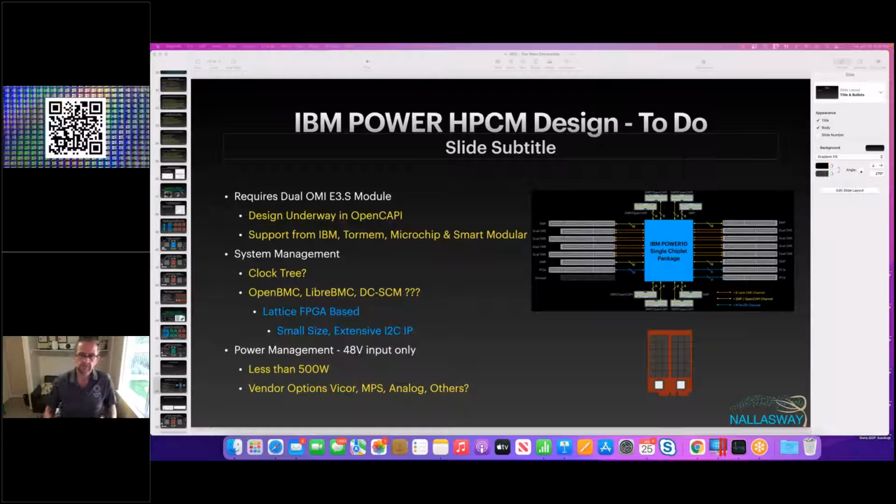Okay, so presumably because it's designed as an accelerator expansion box, you would have the processor and the host on the other side of the host interface bus. That's right. Effectively all that is PCI cables coming out of the OAI box, going to a box above that has your server processors in. And that entity would have the out of band interfaces to whatever the system management entity is out there that's collecting the inventory and doing the fault management.